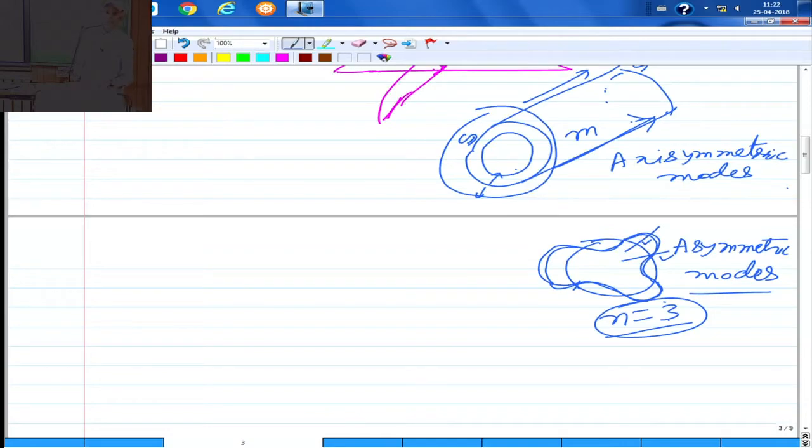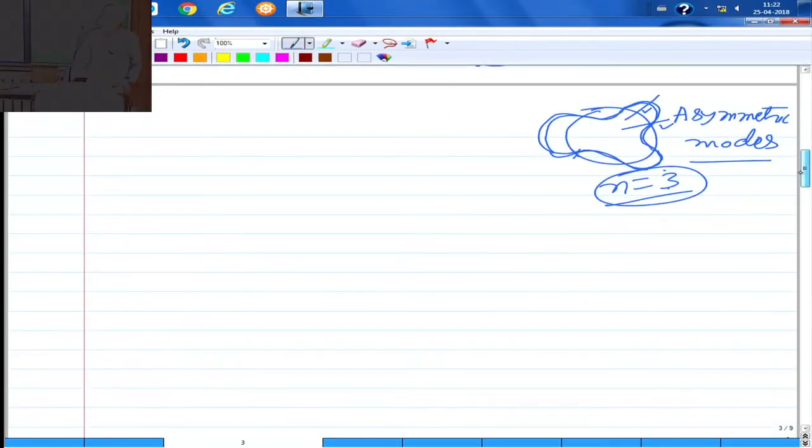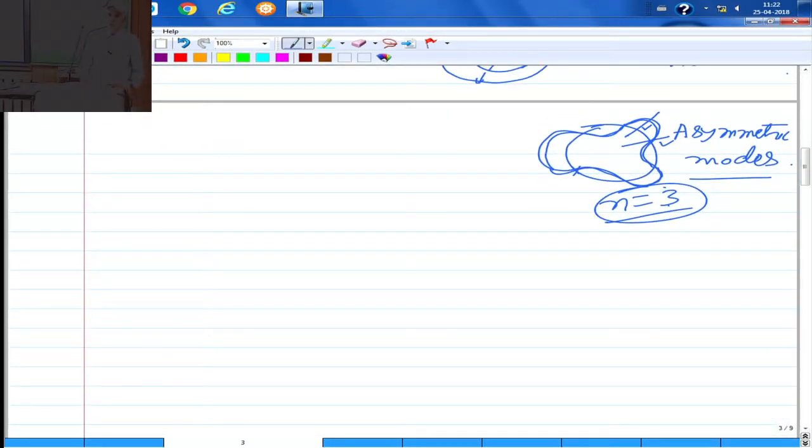Of course when you are doing a force response analysis, depending on the force, because it can excite both symmetric as well as antisymmetric modes, you might have to do a full model. Or if the force is also symmetric, you are sure that it is going to only excite symmetric modes, you can still do the half model like I was talking about for the beam. So this was one question, about the classification of modes. Of course this is part of the dynamics of vibration course you do. Therein you study more details about all these different kinds of modes you get in continuous structures.